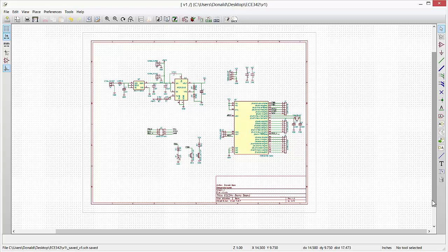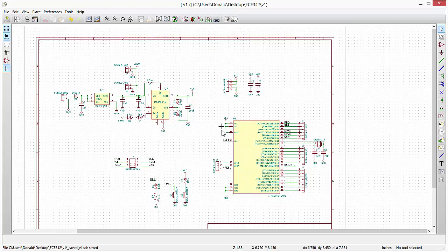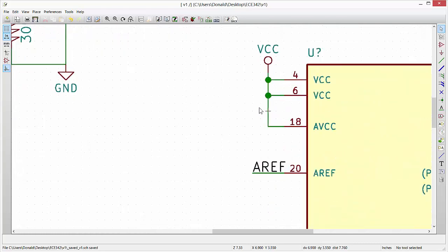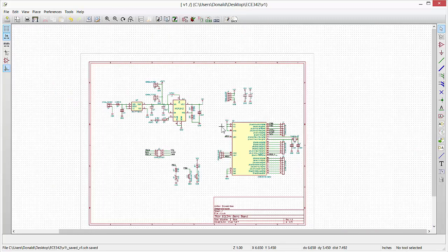At this point, this particular schematic is not known to work. That's just part of how it is sometimes. I did not take the time to verify a couple things that I noticed along the way. I will point some of those out though since we're talking. One of them, a VCC traditionally has an inductor and a capacitor here to isolate it from the digital VCC. I don't think it's going to be a problem. What it essentially does is it makes sure that any analog digital measurements done by this processor are very clean by isolating the two power lines. I still think it'll work, but it might be something I go back and fix after I do a little more research.